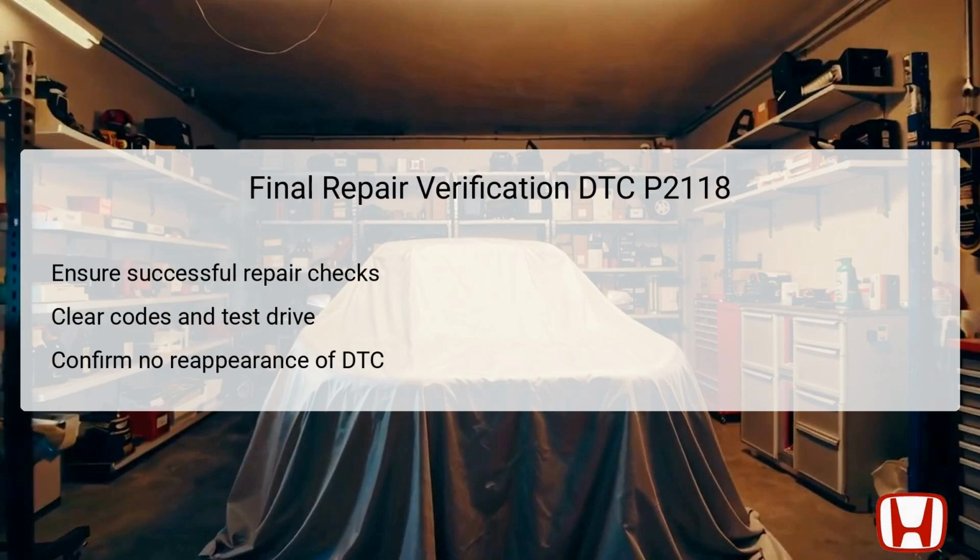After completing all troubleshooting steps for DTC P2118 and performing the necessary repairs, it is vital to execute a final repair verification process. This entails confirming that all checks and repairs align with the standards set by the manufacturer. The technician will clear any fault codes from the PCM using the HDS to reset the vehicle systems.